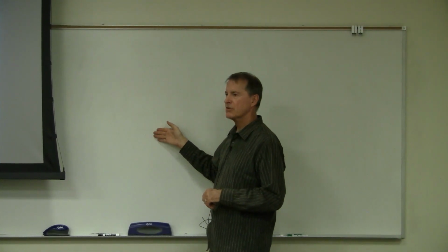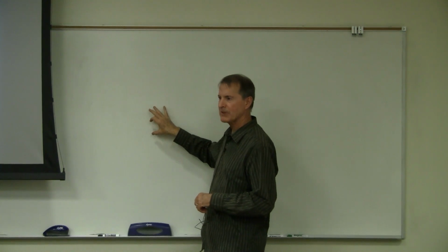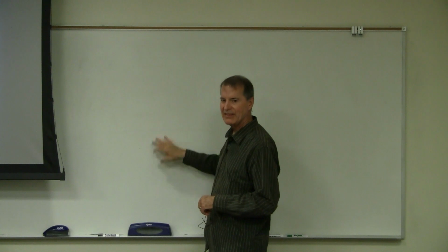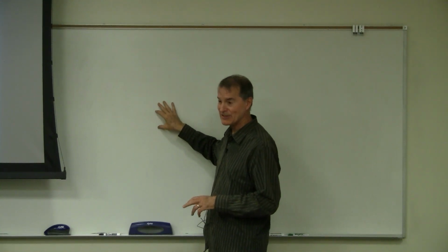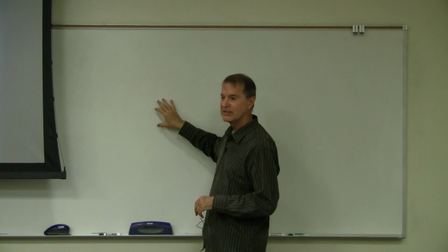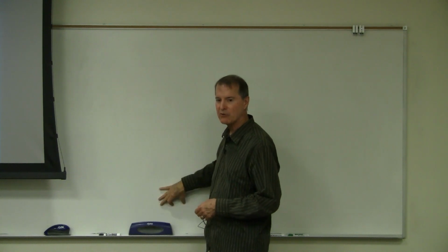In those situations when we know that we're going to transfer the data from the table to a Karnaugh map, it's easier to set up the table in the same order as it's going to go into the Karnaugh map, to minimize the errors that you make in copying over.